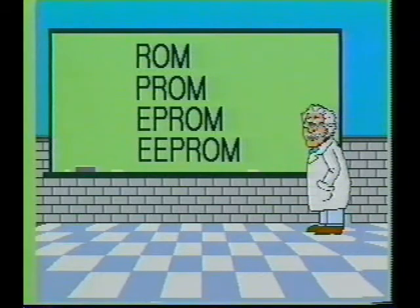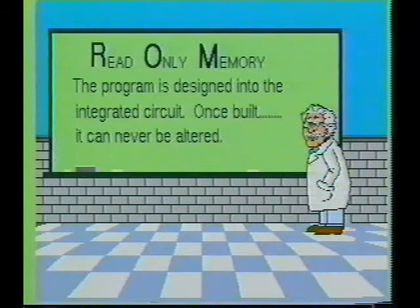Let's begin with the ROM, or read-only memory, since it's the oldest and most straightforward of the permanent semiconductor memory devices. The data contained within a read-only memory device is usually specified by the customer. The IC is then manufactured to contain this data. Once it has been manufactured, it can never be altered. In order to change the information contained within the ROM device, a new IC must be manufactured, then substituted for the old one. Since this is a time-consuming and expensive process, the read-only memory device is economically feasible only when used in large volumes for a thoroughly debugged application.